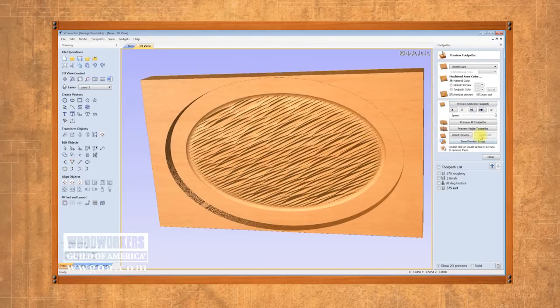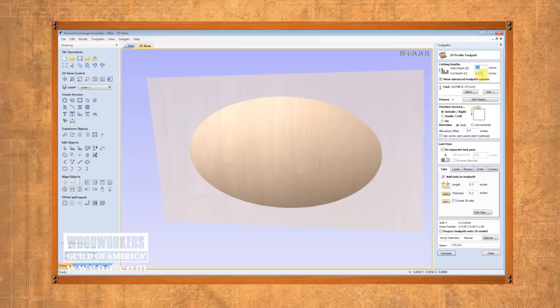So I'm going to undo, and the benefit of being on a computer, double click this piece, and here's the problem. Our cut depth, 0.63. That's a little over ½ inch. Our material's an inch thick. So the bit wasn't told to cut all the way through.